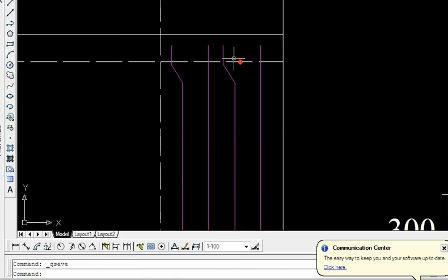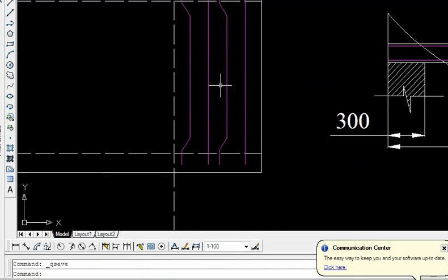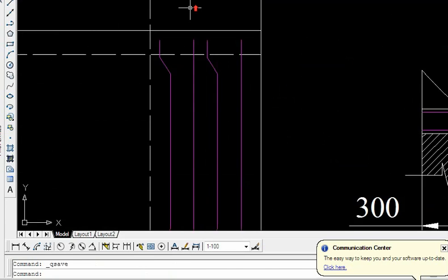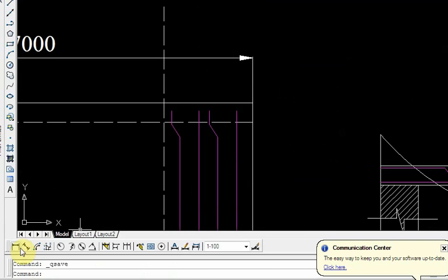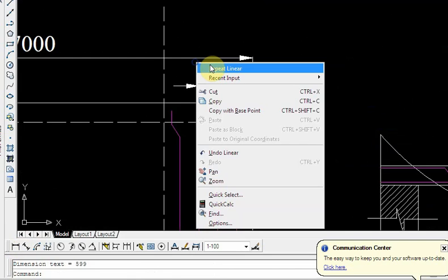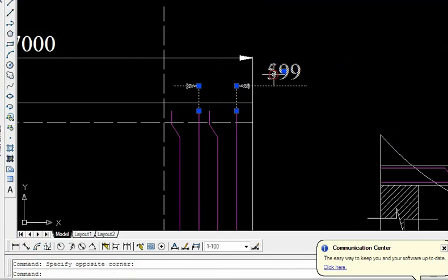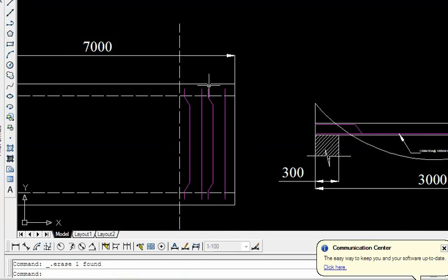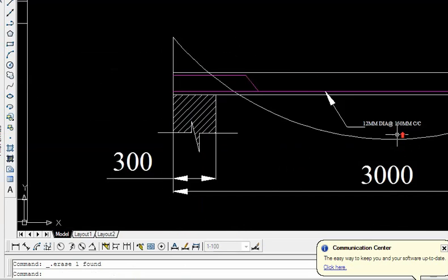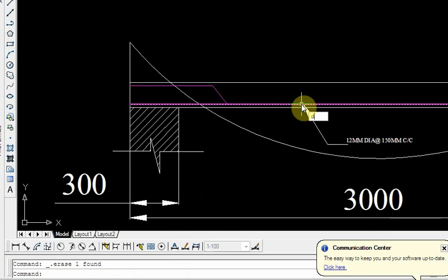If we look at the bottom also, we get spacing as at midspan the spacing will be the same, 12 at 150. When we come to the edge, the main bars are at a distance of 150 and then 300. The spacing at the edges is 300. The spacing at this is also 300. So at the edges the spacing is 300. At the bottom it is 150. This is how the main bars are always provided here. And in this term we got it.